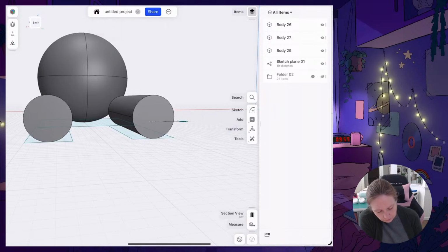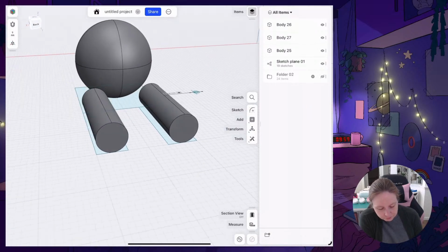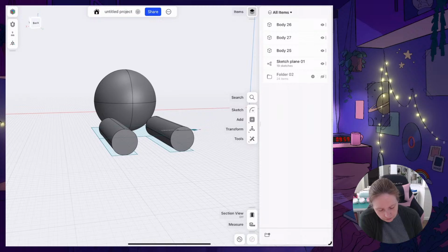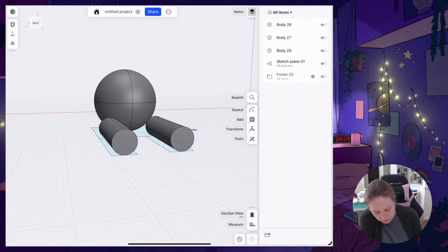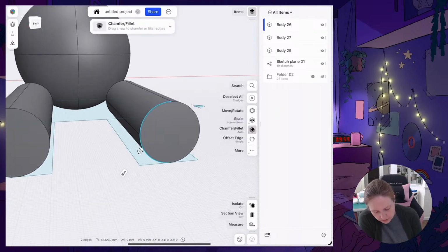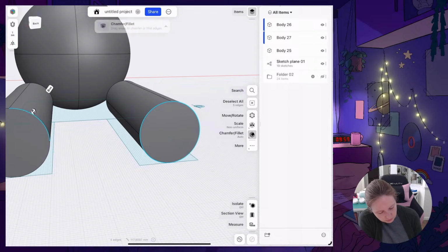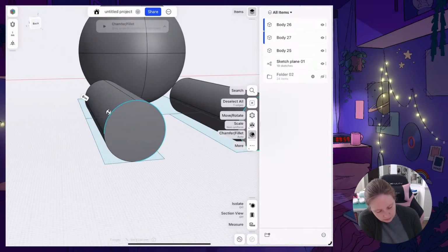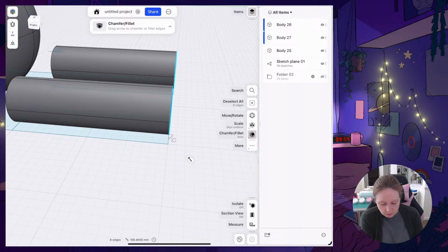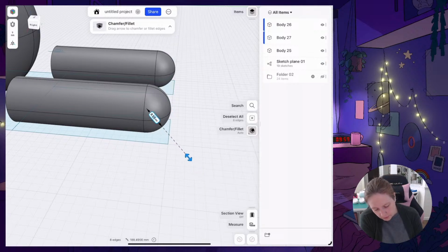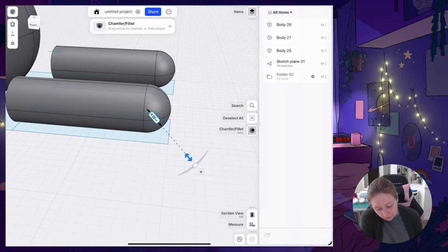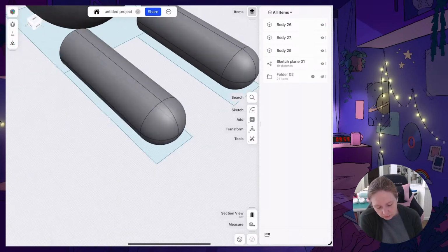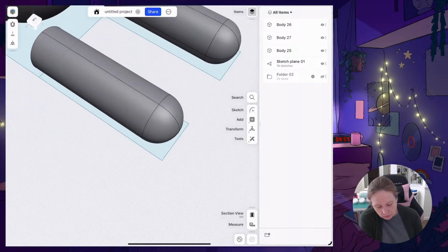There we go. So I've got two cylinders. And then, for instance, I want to create maybe a circular top. Lost my lines. Here we go. All right, I'm gonna chamfer those a little bit as well. It'll usually tell you, so again, we knew it was 30, so 15 should be your stopping point. So that gives me these little round little edges, okay.